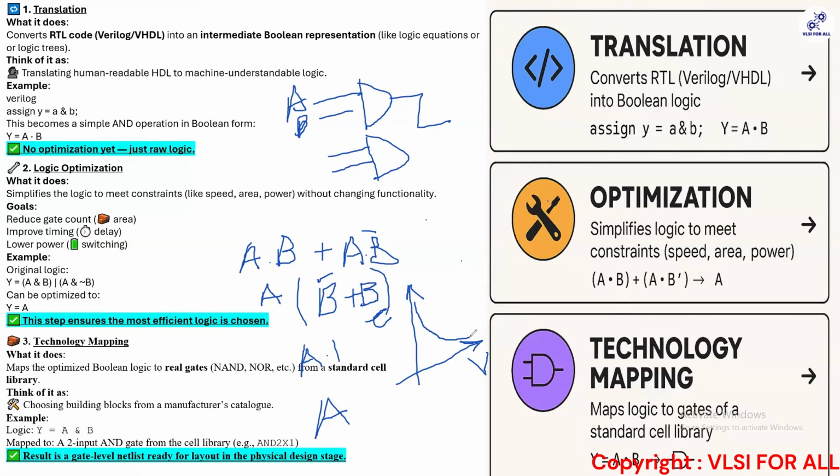Now, when you are doing a project, you do a report timing. You take exactly the same path and report it in two different corners. One you report in the 0.67 corner, and one you report in the 0.6 corner. Exactly the same cell, same path, same start point, same end point, and the logic it goes through should also be the same.